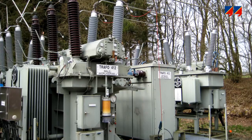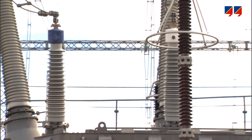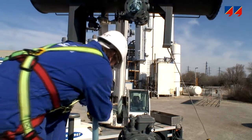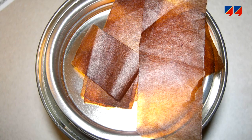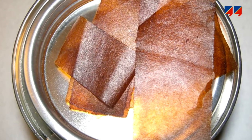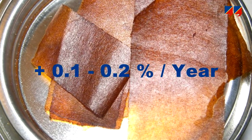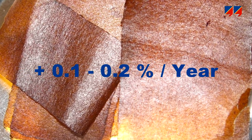One cause is moisture entering the insulation. This can be due to a number of factors, such as the transformer's breathing, which may bring the oil into contact with the atmosphere. Leaky seals, transformer installation, or repair can also lead to an enhanced moisture level in the insulation. The normal aging process may also lead to the creation of water as a byproduct of the breakdown of cellulose. From Segrè's findings, the moisture content can increase by 0.1 to 0.2% per year due to cellulose aging, even if the transformer is completely sealed.